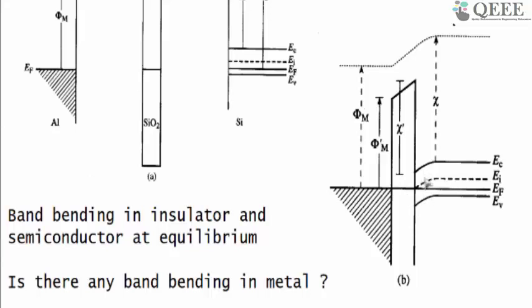Okay, any band bending, you might have studied this earlier. That is why, when you draw a PN junction, inside the depletion region the bands bend. That shows that there is an electric field present. So here you can see there is a band bending near this interface. This is a silicon dioxide silicon interface, and similarly inside the insulator also there is a band bending.